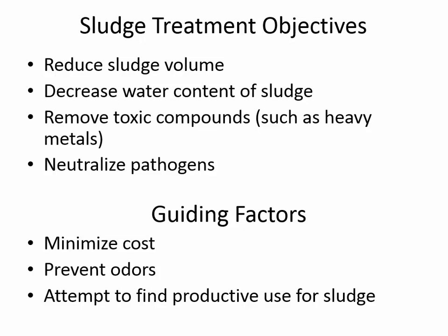The other thing is that when you're working with the sludge solids, you're putting air into contact with organics, and that can really cause a lot of odor issues. If you're way out in the desert, that may not be an issue, but oftentimes these treatment plants are close to populated areas, like the University City treatment plant, which is very close to where people live and work. And so we have to find methods that are cheap, don't cause too much odor, and if we can, we'd love to use the nutrients that are in the sludge, whether it be for crops or fertilizing grass, or other things as well, like using it as a building material.